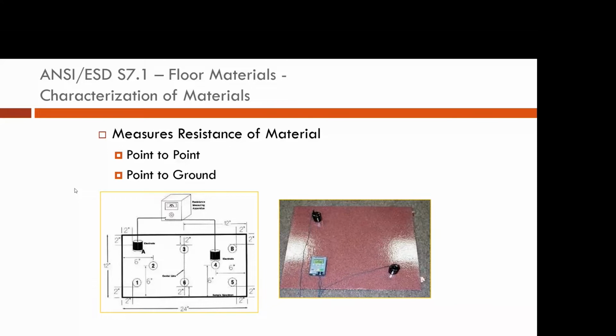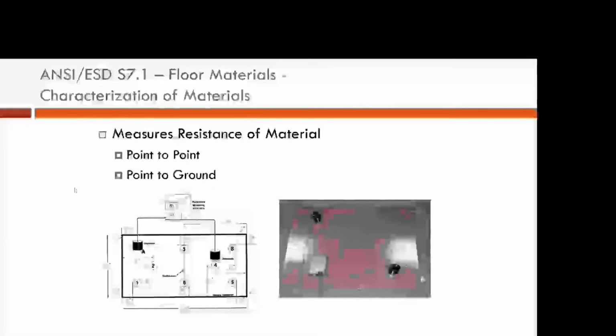Here you're measuring again, is there a tile-to-tile connection? And then next, one of the probes will go to a point to ground, and the other probe will stay on the floor, and you're going to measure, is there a path to ground from the floor to ground?